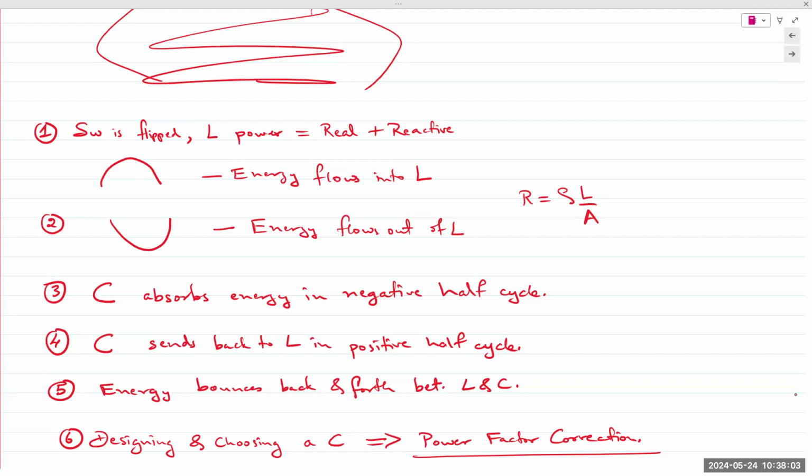So the resonant circuit and the power factor corrected circuit are technically the exact same circuit, but the applications are different. So what we are studying in both is a little bit different. But what I was pointing out was that at resonance, the energy is perfectly balanced between the inductor and the capacitor. So it's a 100% power factor corrected system, which is not possible in real life for an inductive load at an industrial customer.